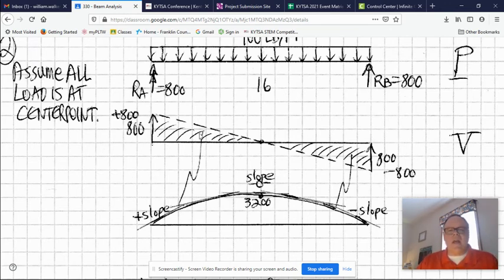Now again, the values of the shear curve represent the slope of the moment curve. So you'll notice here, the shear is positive, but it's getting smaller down to 0. That represents an arc, a curve shape, because the slope starts out large positive. The slope starts tilting over till it gets to the top, and at the top, it has 0 slope. Then the slope starts negative, a downhill slope, and it starts small and gets larger and larger.